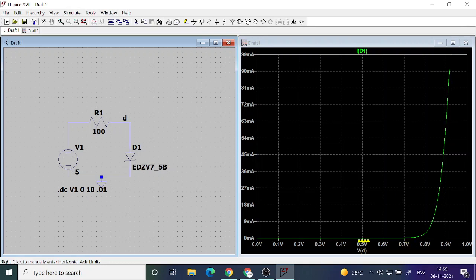this also looks like it is a silicon diode, because you see the cut-in voltage. Cut-in voltage means you can roughly say at what forward bias voltage you have 1 milliampere current. That way you can define cut-in voltage. So this parameter also, after drawing the curve, you can find out and note down in your code. Okay, one is the cut-in voltage, one is the on resistance in forward bias as well as in the reverse bias.